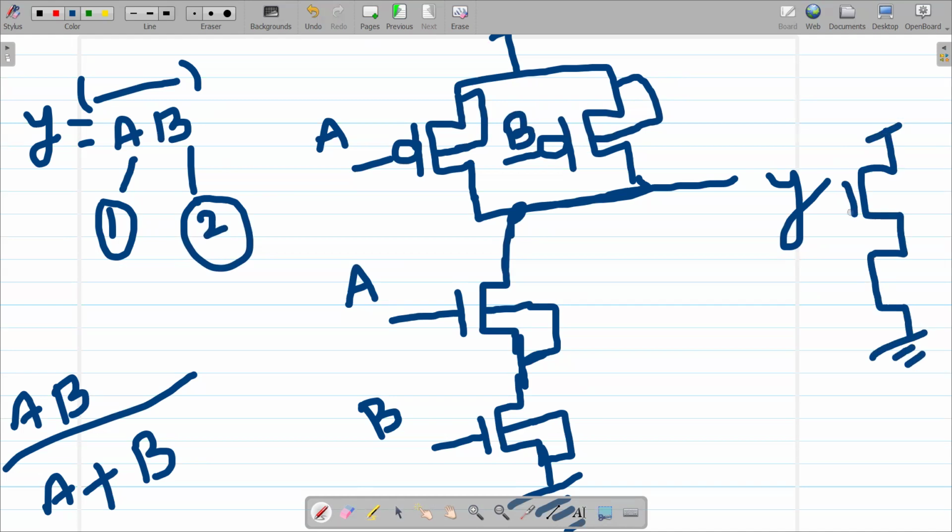So this is your PMOS. PMOS gate is connected to NMOS here. And this output requires to be connected to this gates here. And then you take the output here. This will give you the AND gate output. Okay. So let's now do this one in LTSpice.